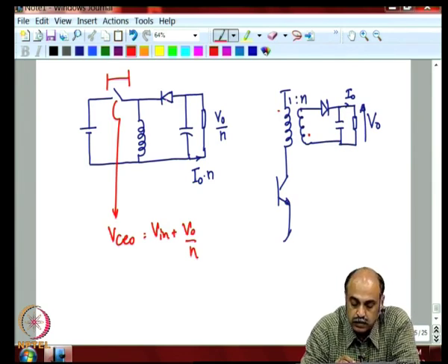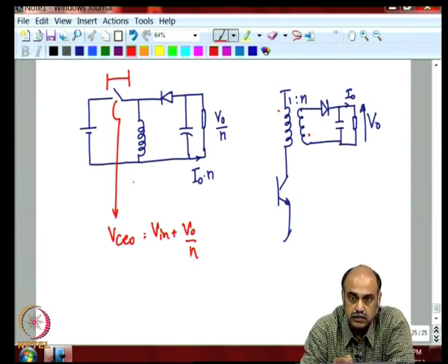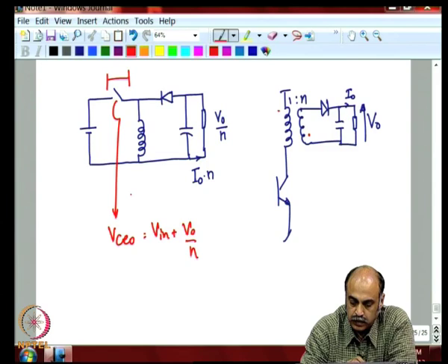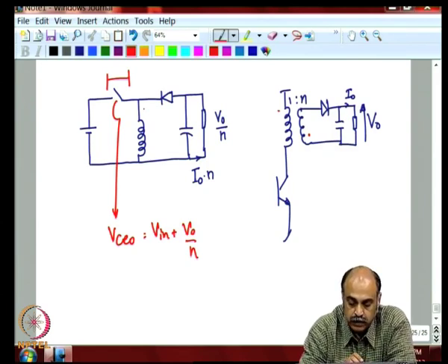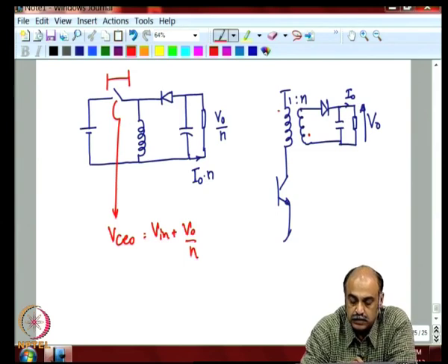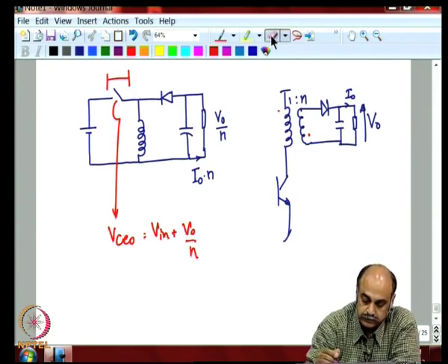And the inductor value can be calculated, and once the inductor value is calculated, find the energy-area product, follow it up with permeance, then the number of turns and the wire gauge. So, once you have decided that, there is a small modification you need to do at the inductor, and that is the K factor.